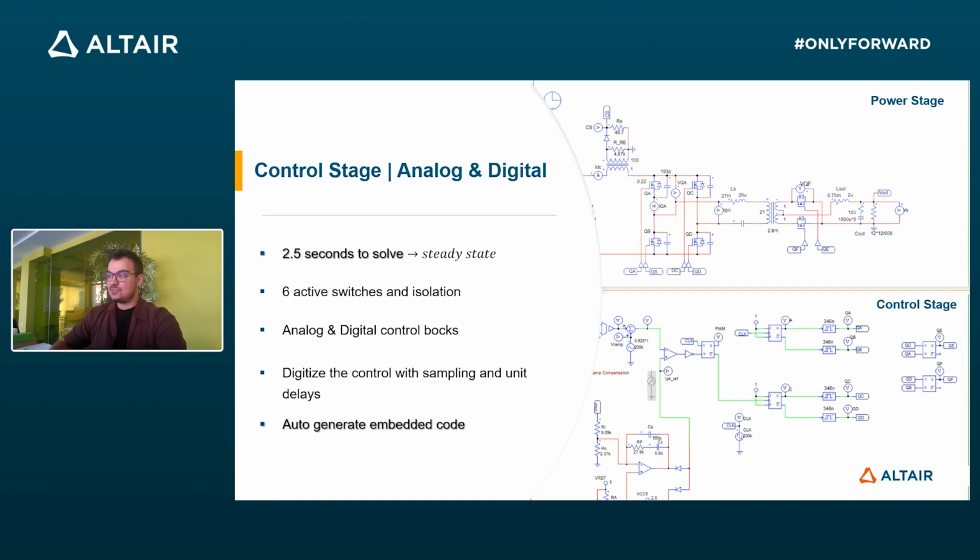Letizia presented us with Flux, so I want to focus today's presentation on motor drives. But please bear with me for a second. I just want to show a simple example of a power supply and how fast it can be solved within PSIM. So in this case, we have a phase-shifted full bridge DC-DC power supply. This can be used for a battery charger application. And this simulation incorporates 6 active switches and 2 transformers with analog control. And it is able to solve to steady state in 2.5 seconds with a 200 kilohertz frequency.